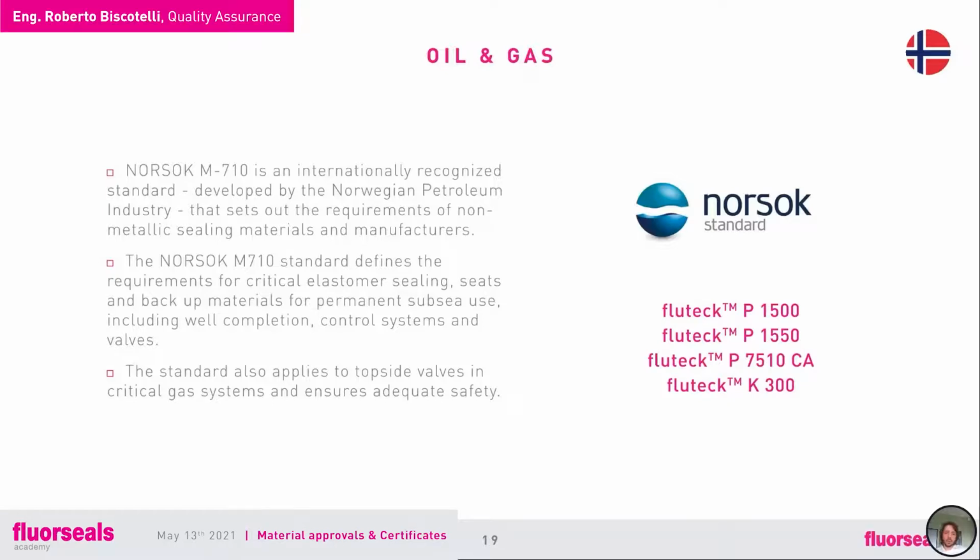Then we move to the oil and gas industry. The NORSOK standard, so the NORSOK M710, is not a regulation per se, it's an industry standard that has been developed by the Norwegian petroleum industry. So they set requirements for non-metallic sealing material and the manufacture of them.